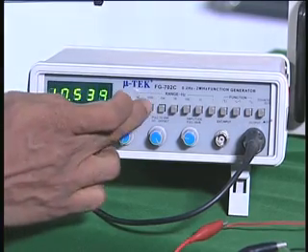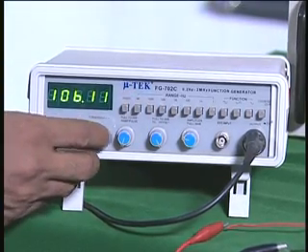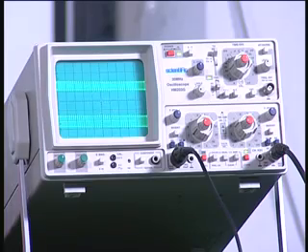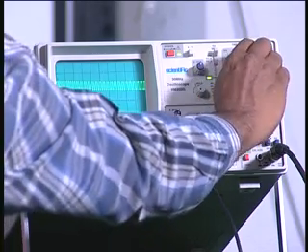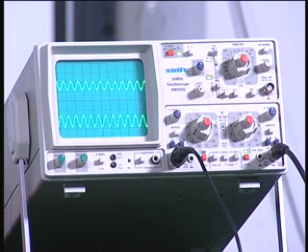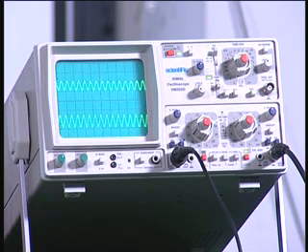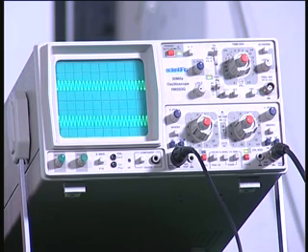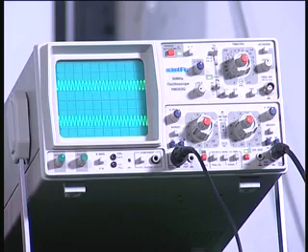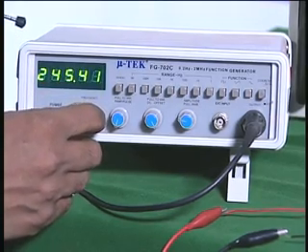Now I go into 100k. I press the 100k. Now let us see. You can see the two signals, they are very close. So now let me increase the sweep frequency, so that again I am able to see a few of the waveforms. And now what I am going to do is again increase my input frequency in the 100 kilohertz range. So we are still having, now it only starts decreasing slowly when I am almost at 300 kilohertz and things like that.